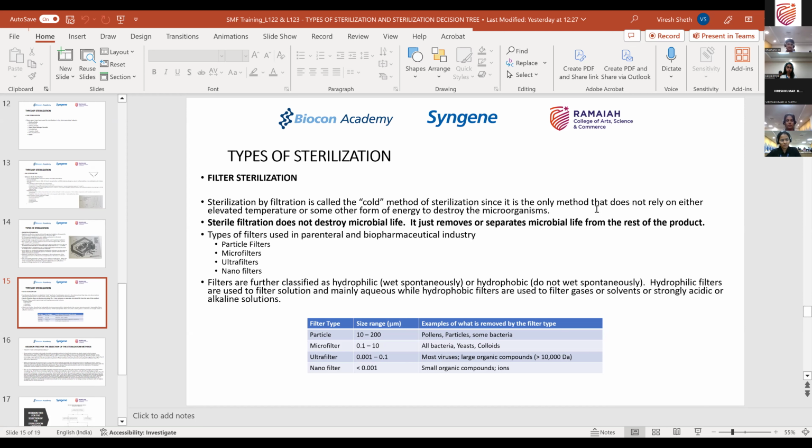Okay. So tangential flow filtration is a technique in which how you send the liquid into the filtration zone. Okay. Tangential flow filtration is nothing but a filter in which the filter and the liquid are in the same vertical or a horizontal plane, meaning that you are sending the liquid parallel to the surface of the filter, and which is at a tangent, right?